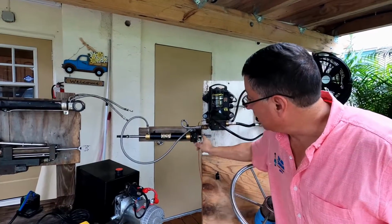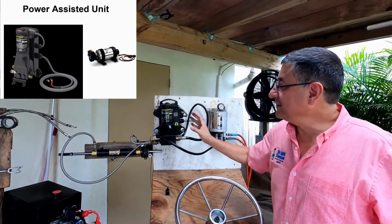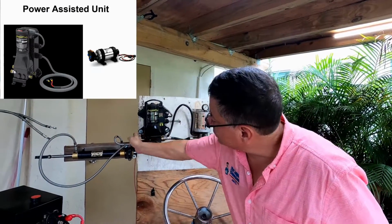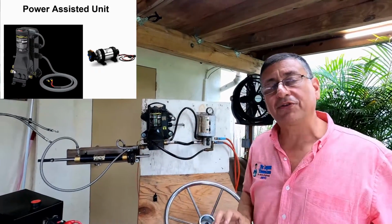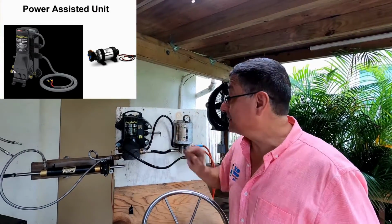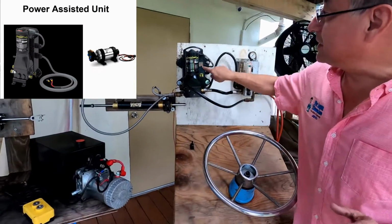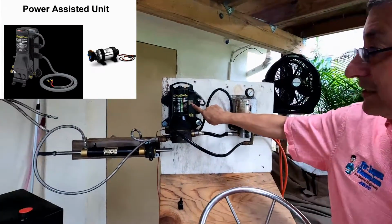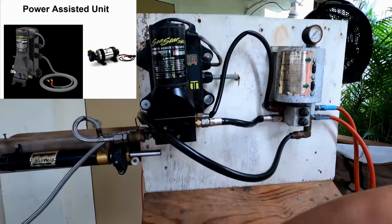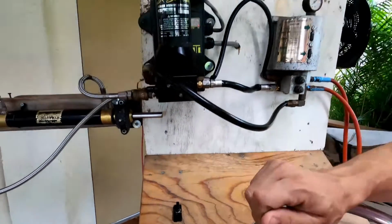This is double port, double shaft. Okay, and what is this? This is a special pump connected in series to add extra pressure in the system. This is the power assisted unit. It's electrical. I can activate that power assisted unit here. Right now it's activated with an external switch like this, or I can activate it directly with the ignition switch.